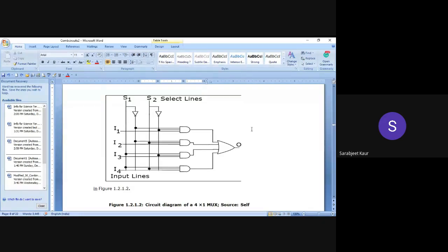In our case, you can think of these I1, I2, I3, I4 as Boolean variables, or switches, to denote when a particular channel is getting information which is to be passed on to the output. So when the signal has to be given that this line contains valid information, then I1 will be set to 1. Otherwise, it will be kept at 0. Is this clear?